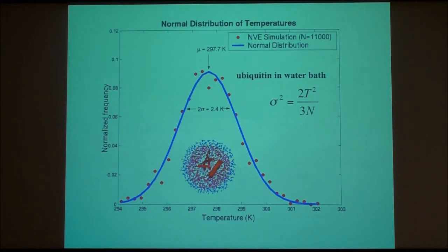Whereas when you come to a very small system, you might have really significant variation of the temperature that you monitor in your simulation system. So don't freak out if you see, oh, my temperature is now 6 degrees less than my target temperature. That's normal. If you increase the size of the system, the fluctuation becomes less, and you will have a sharper distribution. The same is true for pressure. In fact, for pressure, sometimes things are really, really scary. They can really fluctuate a lot.